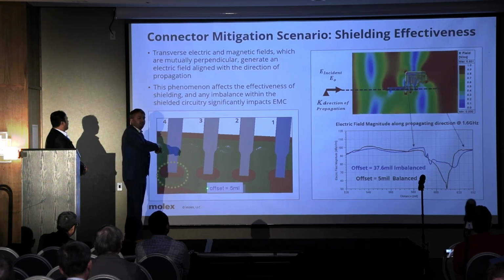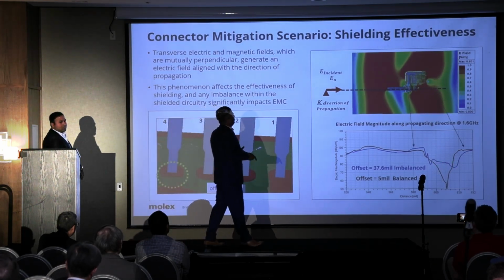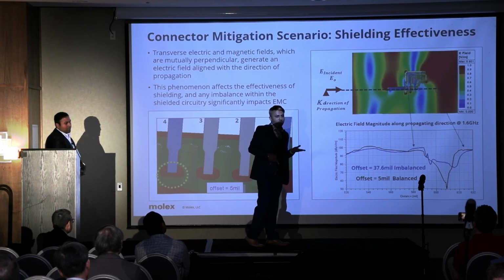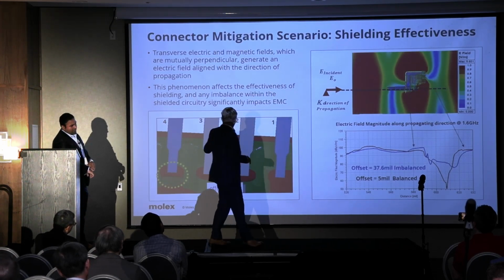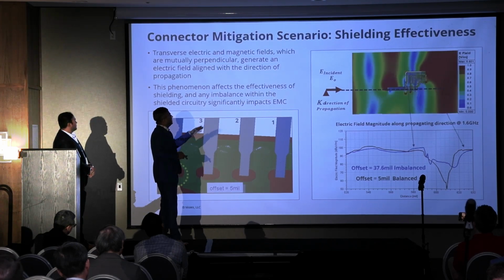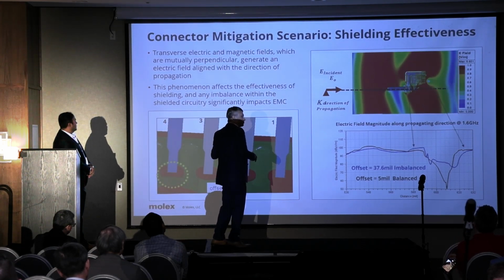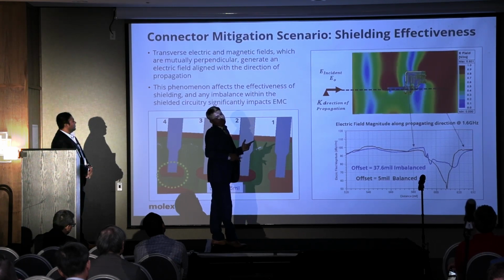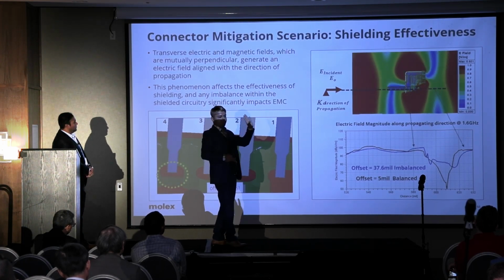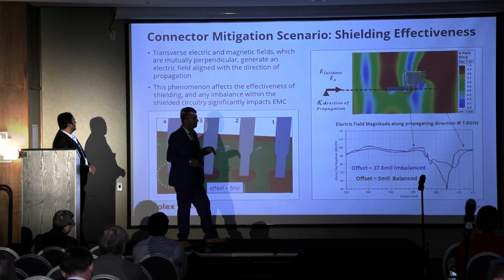because of which it is creating an accidental radiator, in that region, the noise picked up is different when it is grounded and when it is open. So when it is open, the noise that is picked up is less, but when it is grounded, the noise that has been picked up is more. That's because whatever it is seeing on the other end, same thing it has to see on the board end, right?